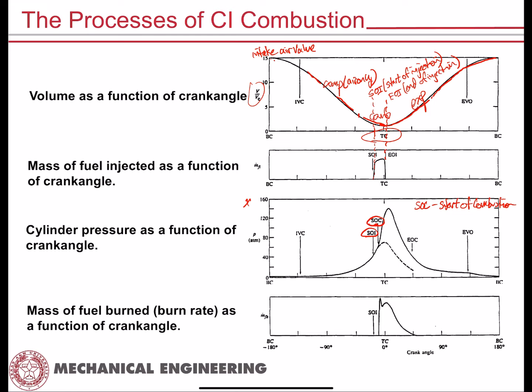Now I can draw this. This is all on the same crank angle scale down here, so all four of these plots are at the same crank angle. If I draw my end of injection down, what you'll notice is that my fuel mixture is actually burning before I end injection. So I'm injecting fuel into the mixture while combustion is taking place.